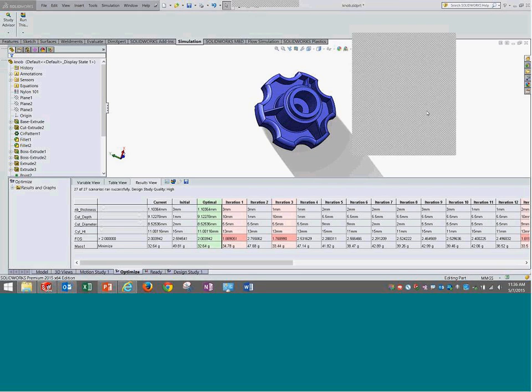In order to simulate the effect of thermal expansion between aluminum and the O-ring gland cutout, I want to know if the expansion of the aluminum will cause a water leak. The question is whether we can simulate a combination of the O-ring and the aluminum, probably the casing in which the O-ring is going to sit. Definitely, irrespective of the material, irrespective of the application, what you saw, these three broader level features are applicable, wherein you can simulate expansion, simulate temperature distribution, and simulate time dependent behavior changes of temperature. Definitely you can do it.